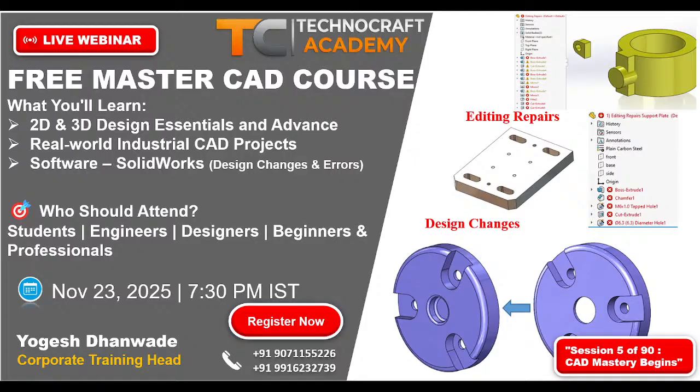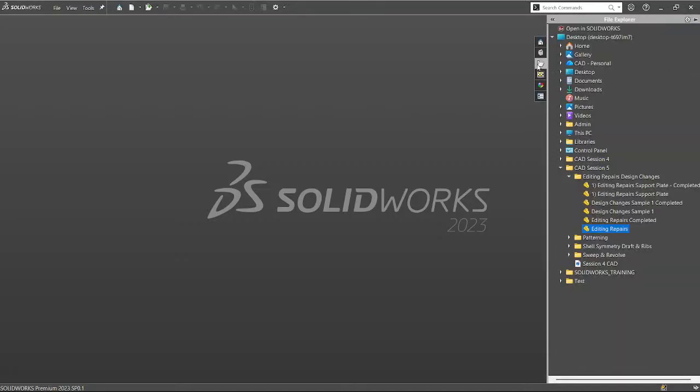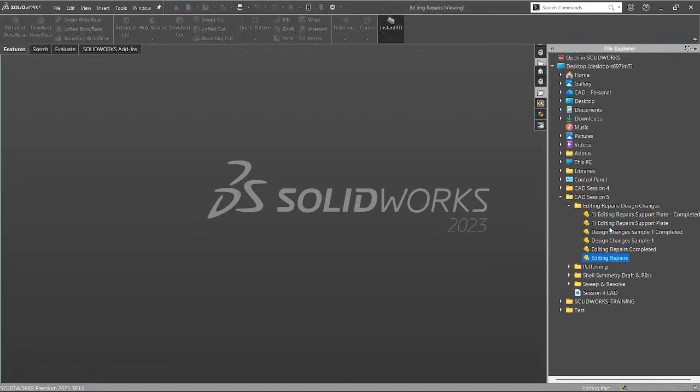I'll just switch to the SolidWorks user interface. One of the advanced options of SolidWorks is that you can directly explore the files from the file explorer. You just need to navigate to the file location where you have placed it. I have it here, and this is my file. You can even have the preview here. If you want to open it, you just double click on this, and it will open. I could see the file is asking me for the rebuild option, meaning I need to update this. I'll just click on rebuild.